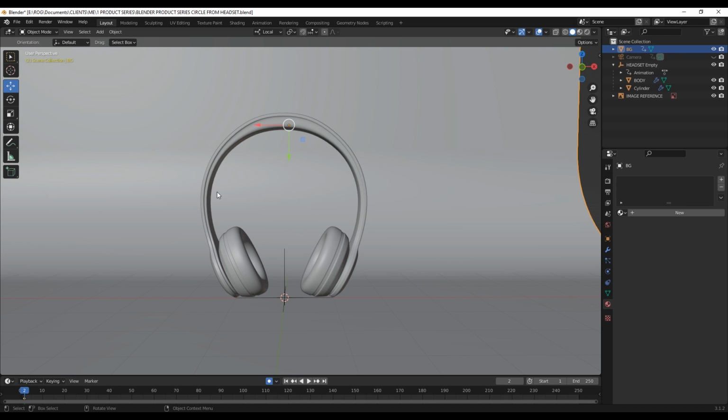So just imagine your current environment in 360, the way the atmosphere is looking and how you have multiple light sources from bulbs, street lamps, and other light sources. So making an HDR environment from that will be like scanning that particular environment and then converting it into an HDRI format, which is usually .hdr or .exr. And then when you bring that to your 3D software, it will use the physical properties, the way that particular environment is lit, to then light your scene. So then you can have multiple light sources and you can have something close to being realistic.